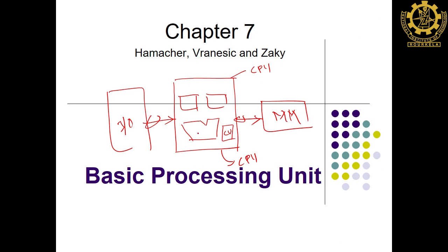So, basically ALU we have studied rigorously before mid-sem, and memory also we have studied, one class left, I'll do it. Now, we will be covering control unit design as I said, and then input output in the last two classes. So, now we will be talking about how we can design the control unit. What is the control unit? Basically the signals it passes. At the right moment the CPU wants to read, so that read signal it has to send. That is what the control unit will do.